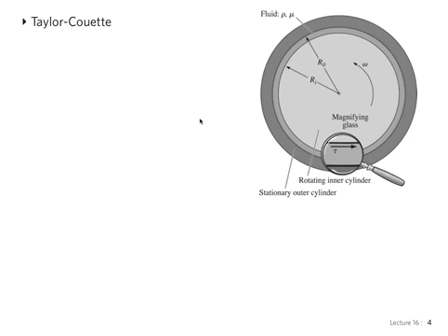and if there is a gap between the two concentric cylinders, as shown here in this cartoon, that is very thin compared to the diameter of the cylinders, then you can neglect the effects of curvature, and it's almost the same situation as two infinite plates. Okay, so he suggested to look at this case. It's called Taylor-Couette rather than just Couette.